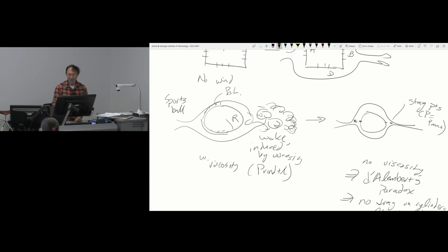And I think that makes sense that they die in the front, but because there's no viscosity, the front and the back have to look the same, and there's actually a stagnation point in the back. So those are basically where P is equal to P max, and as a result from Bernoulli, if pressure is the maximum, remember we're talking about conservation of energy, if you've got maximum static pressure energy, then you have U is equal to U min. And conversely, at these two points, you have pressure equal to P min because your U is equal to U max.